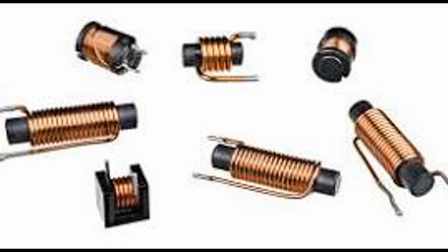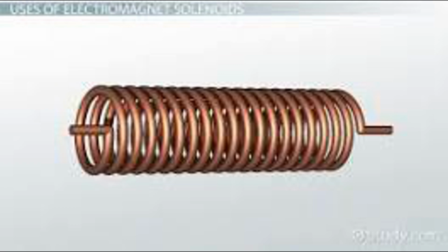AC/DC solenoids, classified by the type of current, used in either high-power or low-power systems. Tubular solenoids, enclosed in cylindrical housings for greater efficiency, used in high-force applications. Open-frame solenoids, simple and cost-effective for light-duty tasks. Each type of solenoid serves a distinct purpose, making them versatile components in various mechanical and electronic systems.